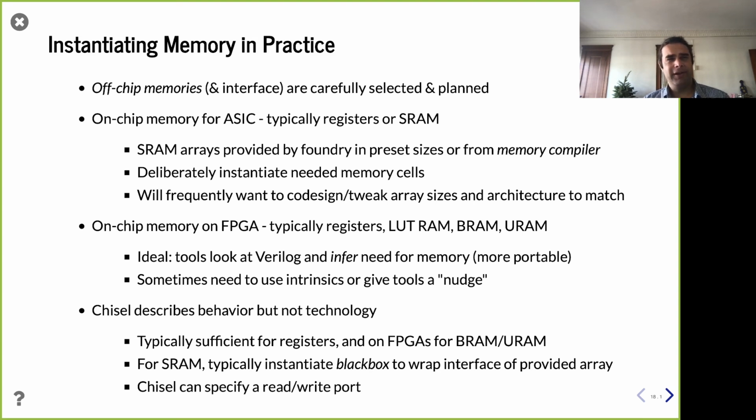And of course, you're thinking, wait, Verilog? I'm not doing Verilog, I'm doing Chisel, right? Yeah, so Chisel, if it's used correctly, you can get this right, but you actually can use Chisel to cause this inference to break. So sometimes you need to give what's called an intrinsic, to tell the tools, I definitely want this kind of memory here. Hopefully you can avoid that.